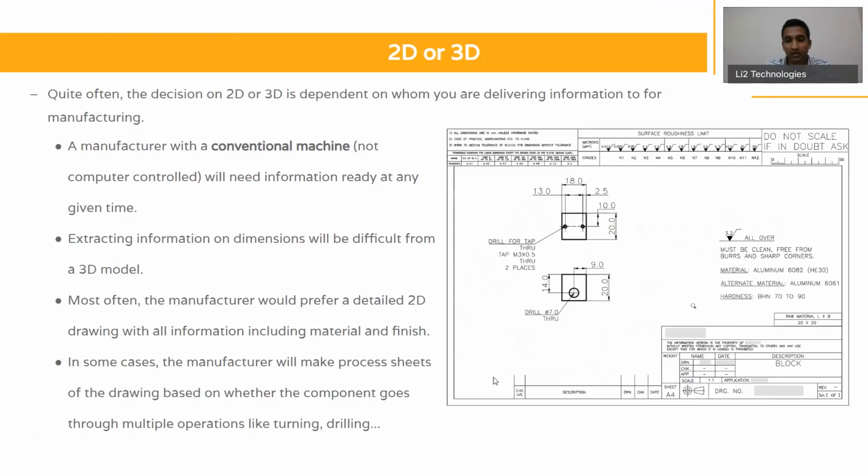There's an area in this template which is generally used for version control. So for example, today I have the dimension of 20 mm here. Tomorrow if I want to make it 40, I can make it 40 and just give a version control over here saying I changed the dimension from 20 to 40. This gives a good understanding to the manufacturer as well, or to people who continue with the design, to say why a change was made.